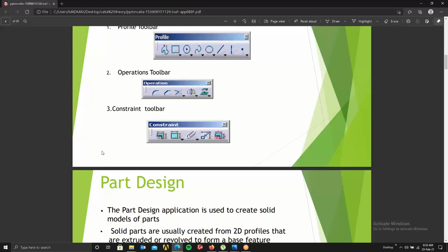See, we have two different constraints. One is dimensional constraints and one is geometric constraints. Okay, these are two different types of constraints. One is dimensionally constraining it. Dimensionally constraining means if you have a center origin point, it will be stationary. So it's a fixed point, origin point. So what you can do is you can dimensionally constrain it with respect to the origin point. You can give the length, the breadth, the height, and all those things, and you can just constrain it with respect to the origin point, and it will be totally constrained.